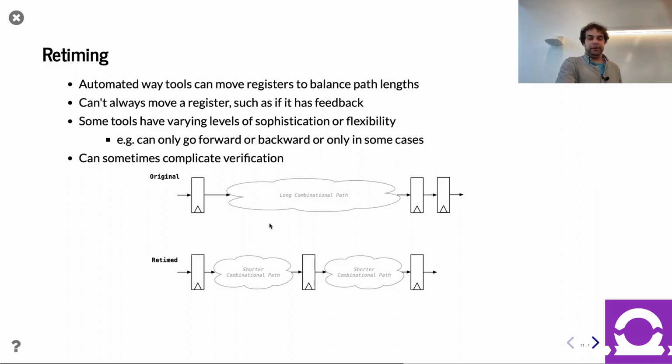Now, in terms of how this is allowed, it depends, right? From the input point of view and the output point of view, the semantics are unchanged. Data goes in, it comes out X cycles later, that's unchanged. So from that point of view, the semantics are not changed. However, the content of the registers in between is now different. So if someone's expecting certain values in registers, because you have logic on both sides of them, you have to be prepared for that. So that's where the devil in the details is. The retiming question is how do you move registers through logic networks to make sure that if people depend on the values of the intermediate registers to get the right results, it still works.